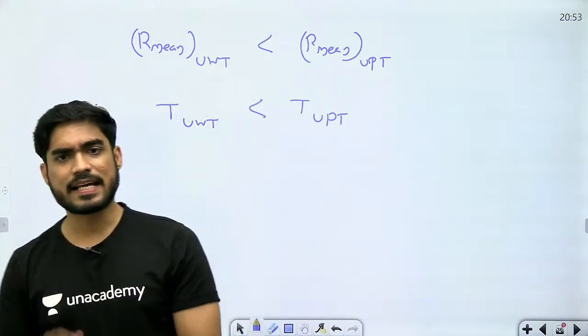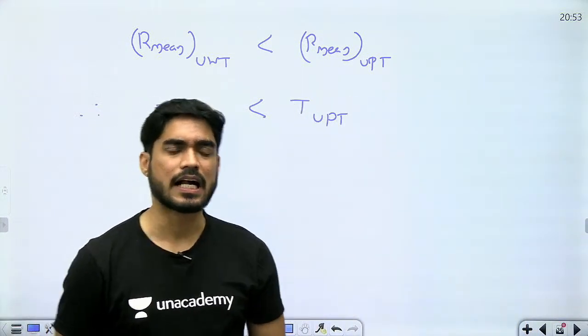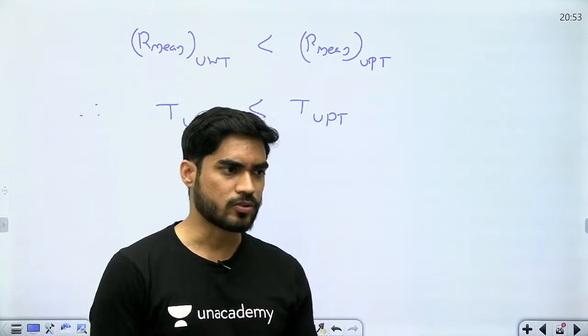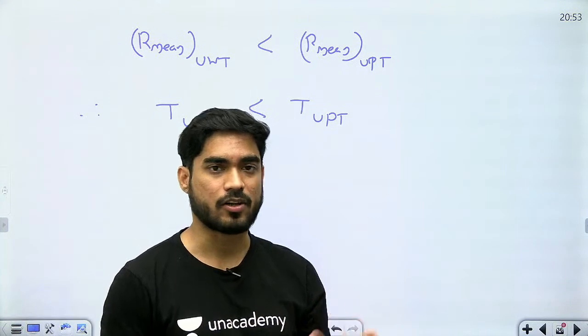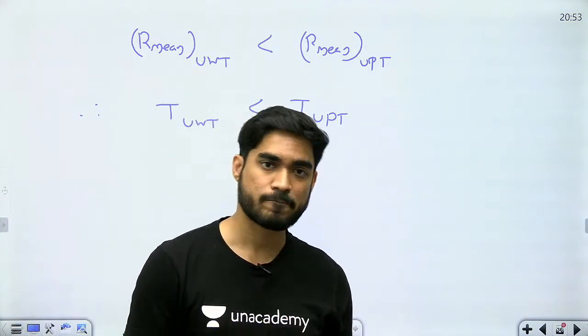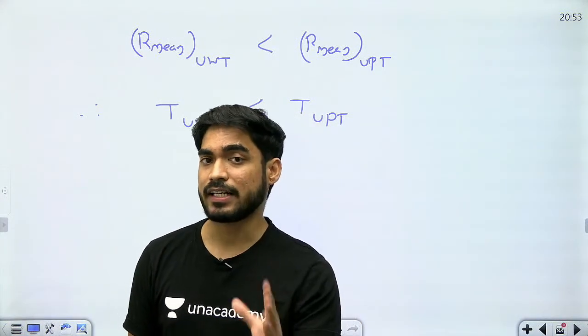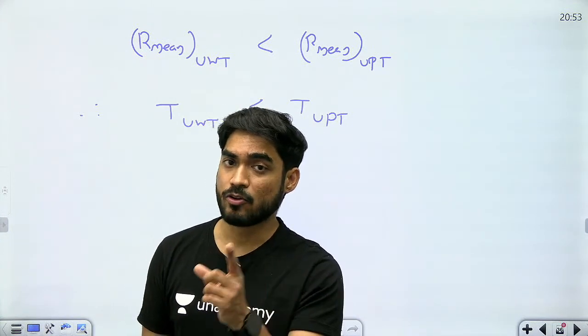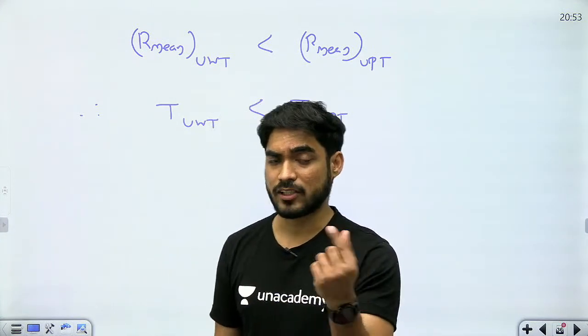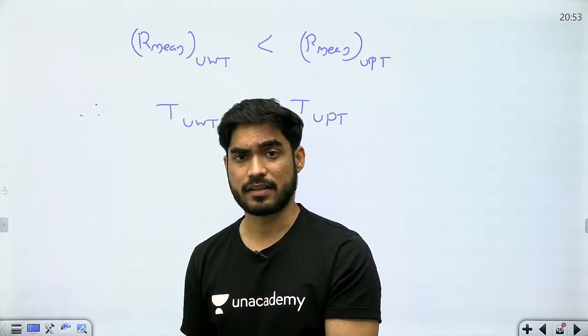Right now it is transferring 100 Newton meter torque. You need 100 Newton meter torque. It is transferring 100 Newton meter torque according to pressure theory, but only when pressure theory is applied. When uniform wear theory becomes applicable, the torque will reduce, right?